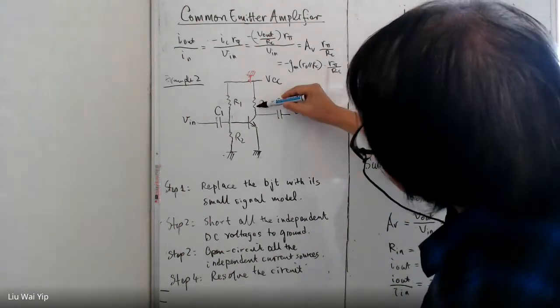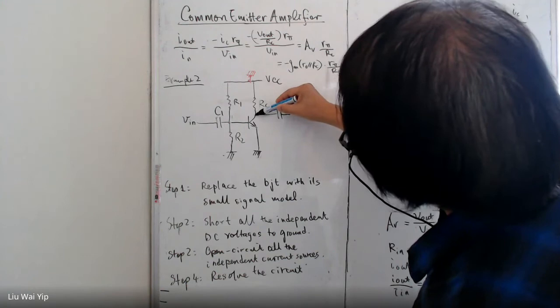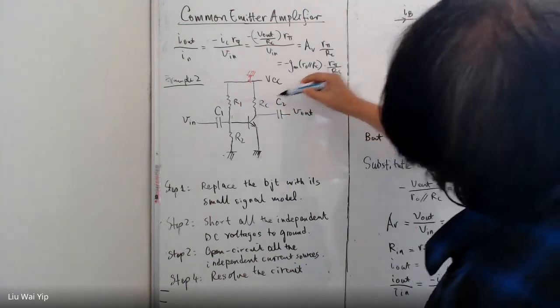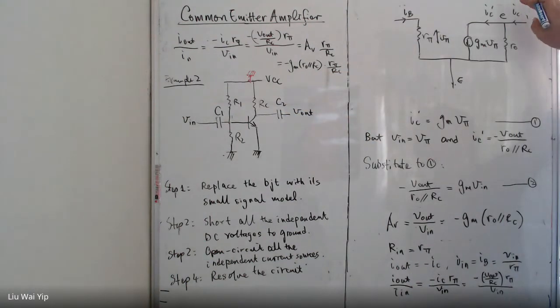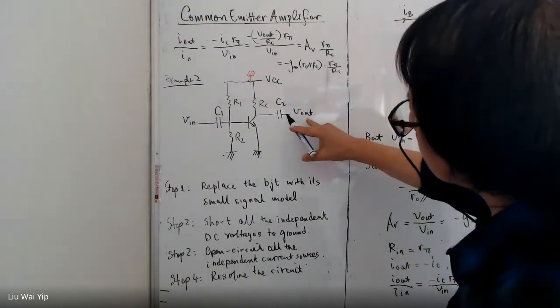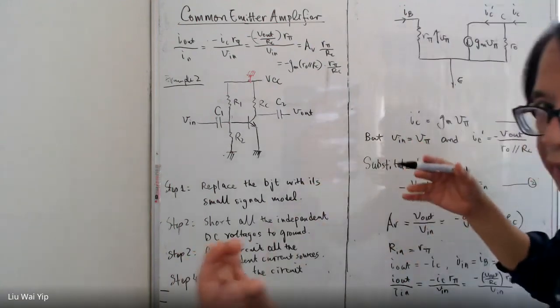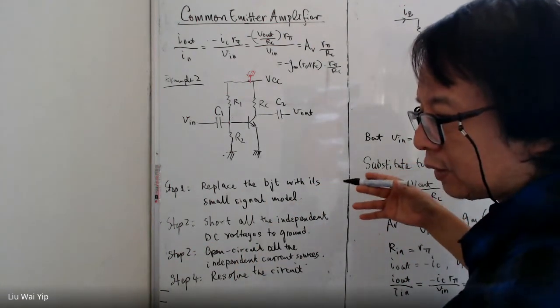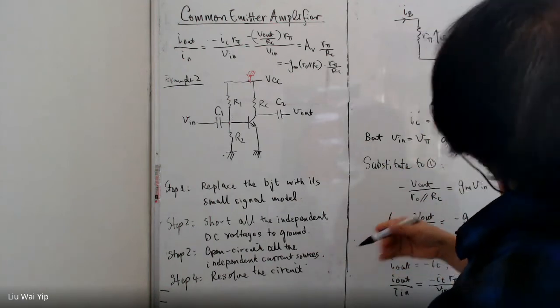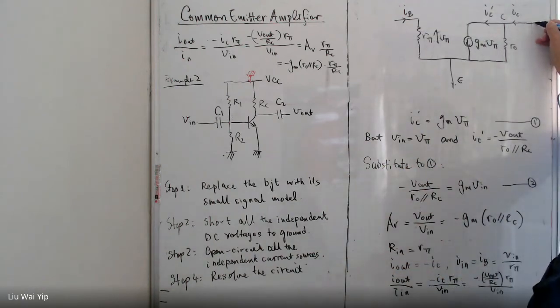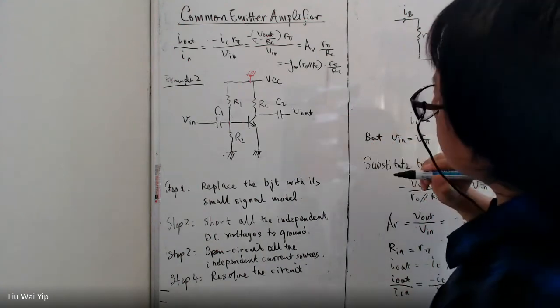And with this in mind, we have a resistor, and this point here is the collector. The collector is the point where we tap the output, a high frequency AC signal. The capacitor is conducting, just like a short wire with very low impedance. So we just approximate the circuit. This is what we do.